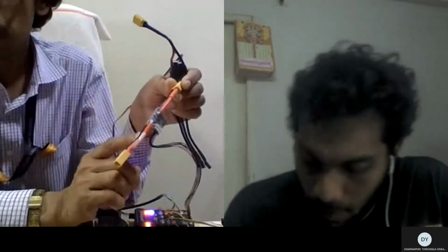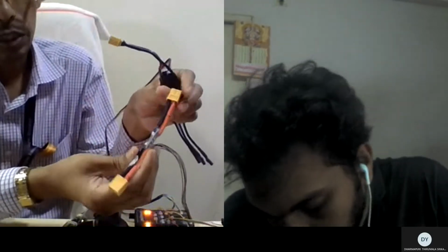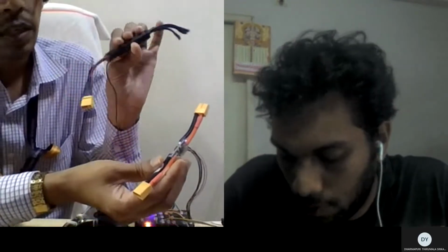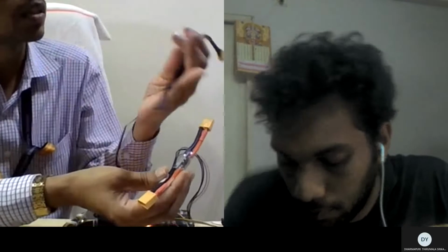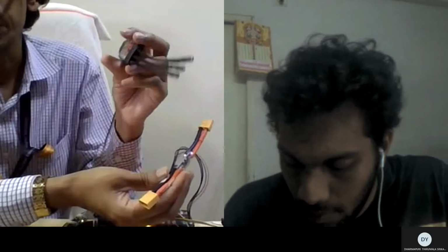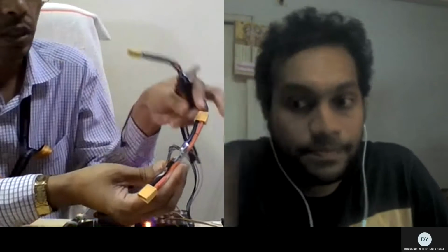I have some connections here. There is called a power module. If you check this, there is a power module. Okay, so this power module is there to protect your speed controller also. Sometimes damage to your speed controller is observed during testing. When you connect the battery directly with the speed controller, there is a chance this will get damaged because at the end there will be a Zener diode inside. Okay, so that mostly gets heated and will damage. So for this you should have a power module.